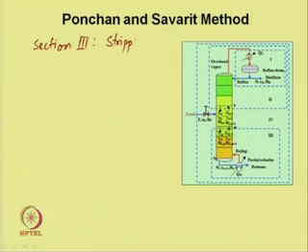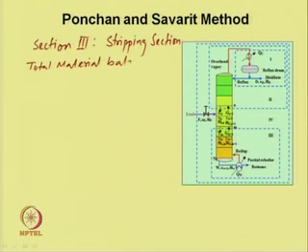Stripping section. The total material balance in this section, we can write: L_m bar would be equal to G_(m+1) bar plus W. This is 10.9.